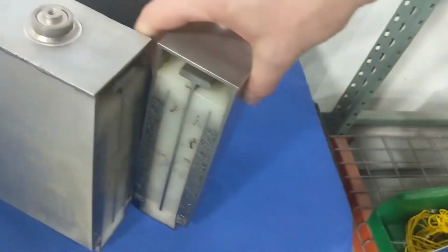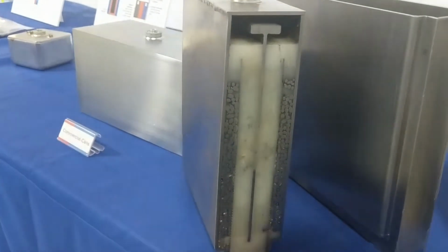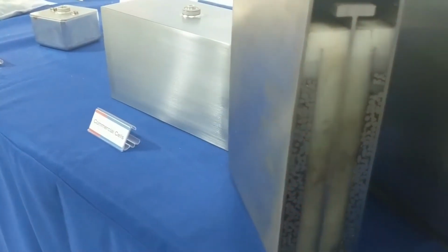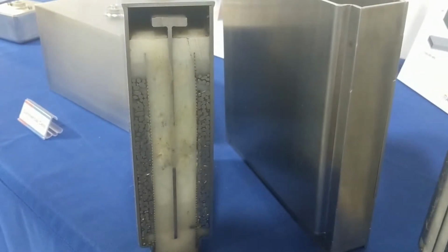And if we cross-section it, and this is just for demo purposes, you get a sense of what it looks like on the inside of the cell. So the cell has this negative current collector down the center, and then the antimony particles are located in the two bays on either side. And so that's really the internal configuration of the components, with the antimony, the salt, and then the calcium wets onto the negative current collector, current lead rod in the center of the cell.